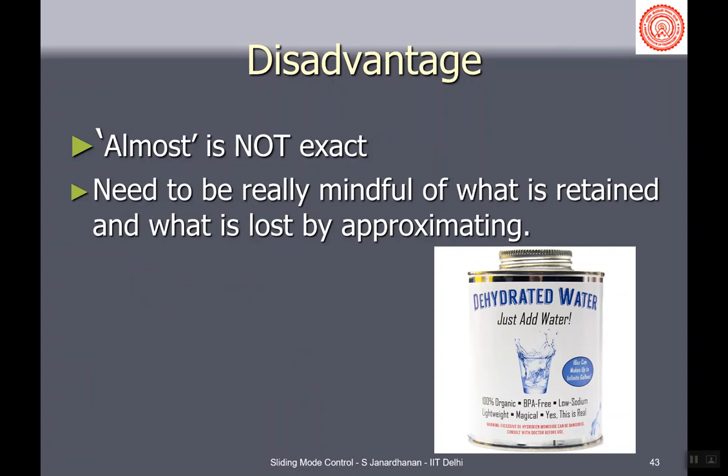We had started with finding a control that would be robust and relatively simple. We ended up finding that the implementation of that control requires a discontinuous signal, a relay, and the relay would cause chattering. Chattering can be reduced by smoothing the sign function, but in the process we lost the basic thing, robustness.